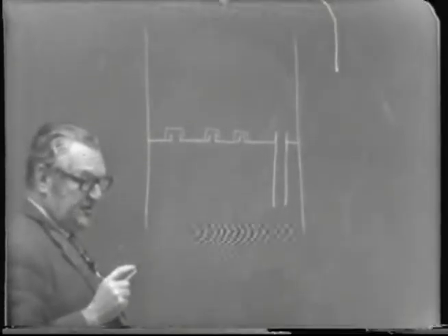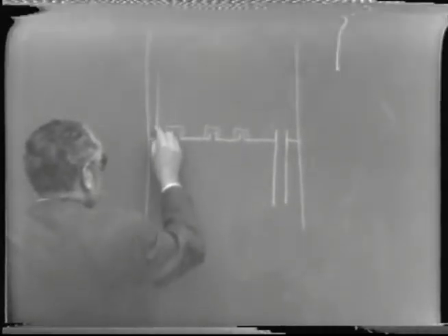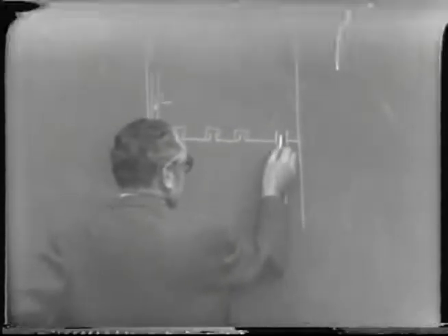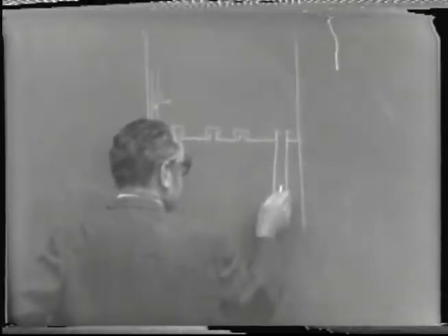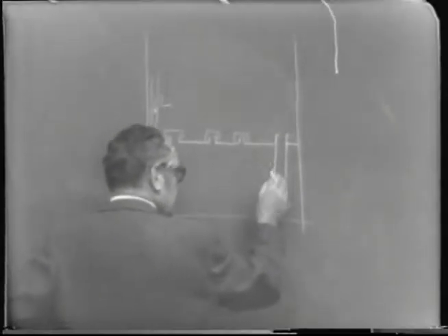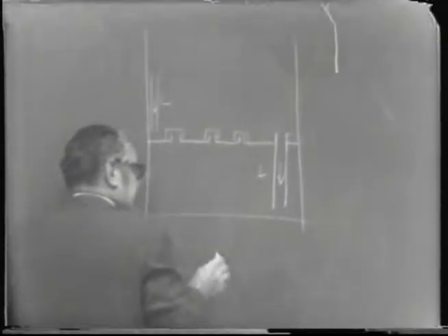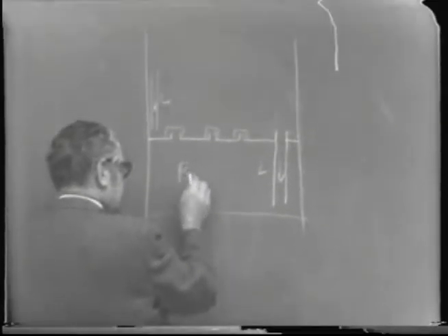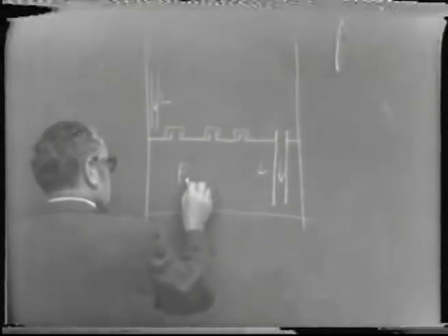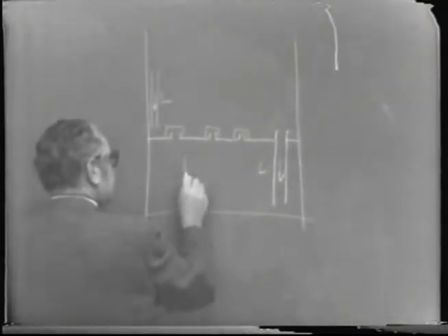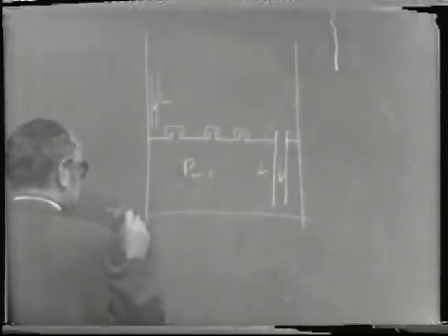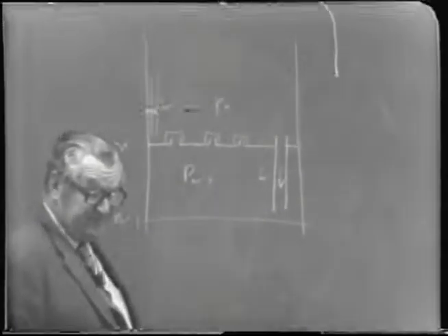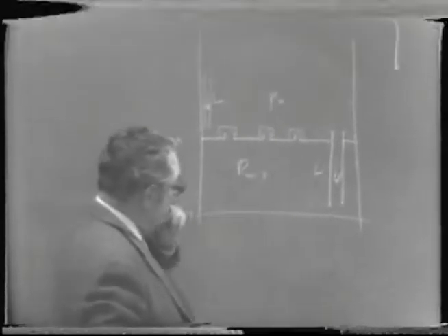Schematic illustration of a bubble cap tray in which we have a liquid being delivered from the tray above, and then we have an overflow here to the tray below. And we pointed out that there's a pressure drop across the column. The pressure for plate N+1, if this is N+1, has to be greater than the pressure above at the tray above. And this represents a pressure drop per tray.